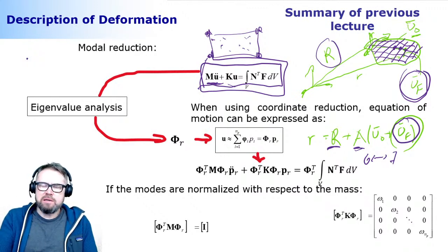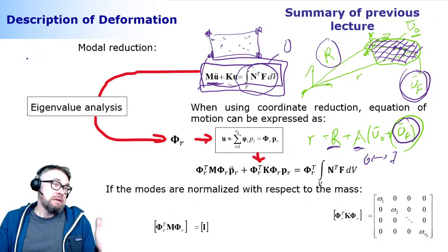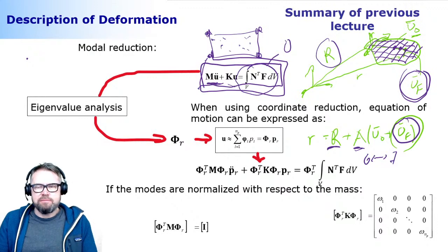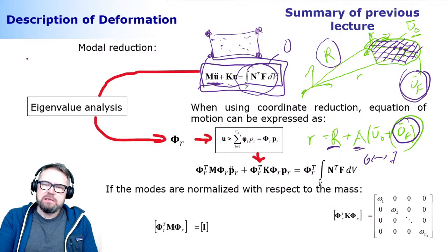Because to conduct the eigenvalue analysis, the externally applied forces are set equal to 0. There are no forces applied to the system. That already tells you this is all about properties only, not absolute responses. And because it's about properties, you're looking at inertia versus stiffness.